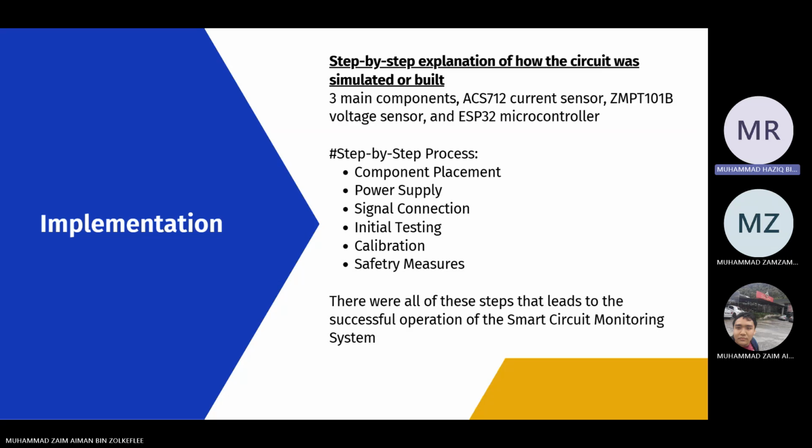The fourth one is initial testing, which is to upload the provided Arduino code to the ESP32 and open the serial monitor in the Arduino IDE to check whether the Wi-Fi connection is successful and verify that analog values are being read from the sensor.